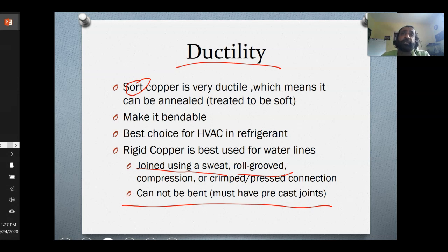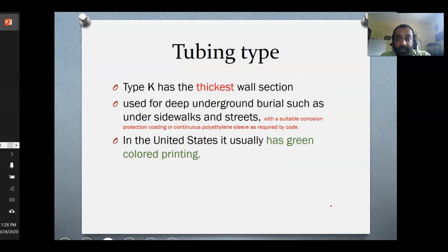So it's good to just cut and use pre-made fittings to make the connection much better. If you're doing refrigerant, you can run the refrigerant line from the inside of the house to the outside, and you want to minimize the parts where the pipe is not going in a straight line, going sideways. So try to make it as neat as possible.